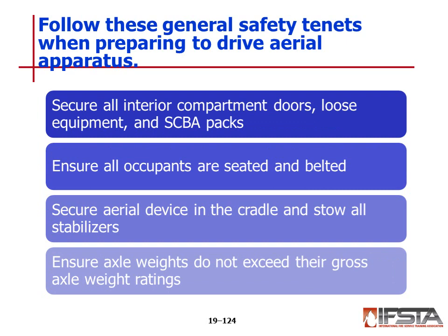Secure all interior compartment doors, loose equipment, and SCBA packs. Ensure all occupants are seated and belted. Secure the aerial device in the cradle and stow all stabilizers. Ensure axle weights do not exceed their gross axle weight rating.